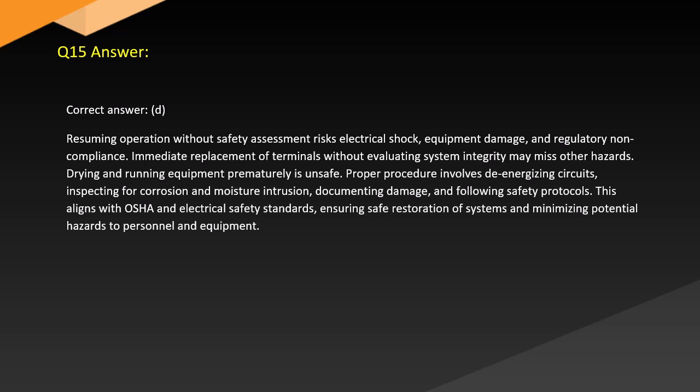Answer. Correct answer. D. Resuming operation without safety assessment risks electrical shock, equipment damage, and regulatory non-compliance. Immediate replacement of terminals without evaluating system integrity may miss other hazards. Drying and running equipment prematurely is unsafe. Proper procedure involves de-energizing circuits, inspecting for corrosion and moisture intrusion, documenting damage, and following safety protocols, in line with OSHA and electrical safety standards, ensuring safe restoration of systems and minimizing potential hazards to personnel and equipment.